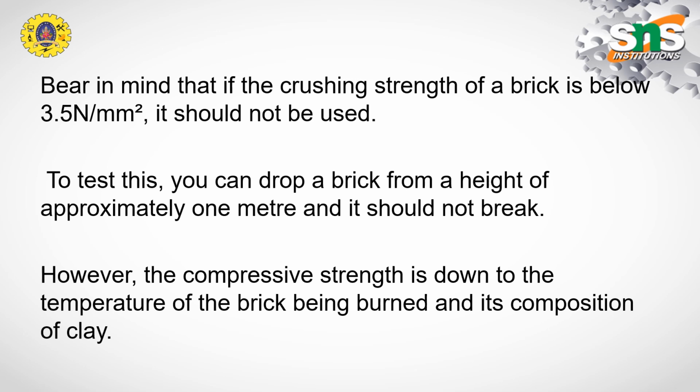You can hold a brick at our height and drop it from that height, approximately 1 meter. When we drop it, it should not break. If it breaks, then it is not a good brick.